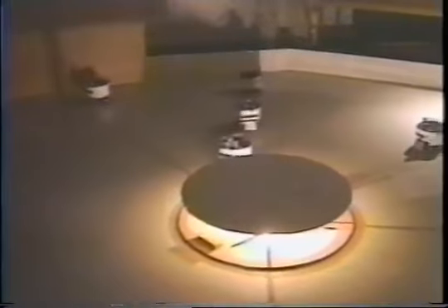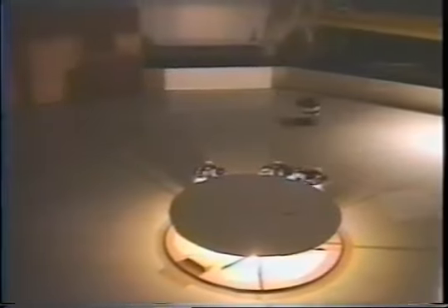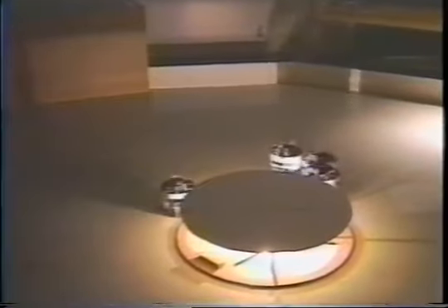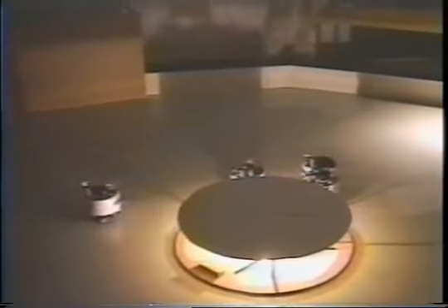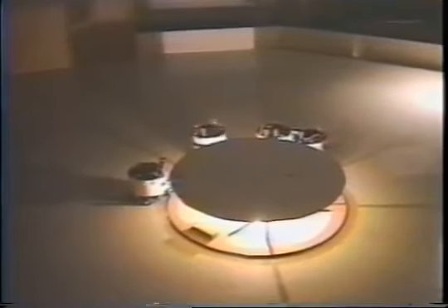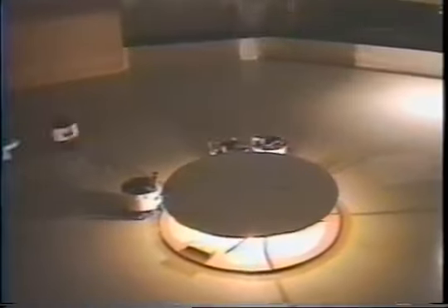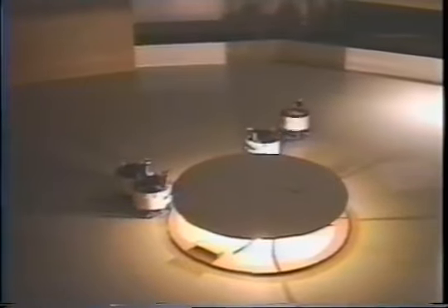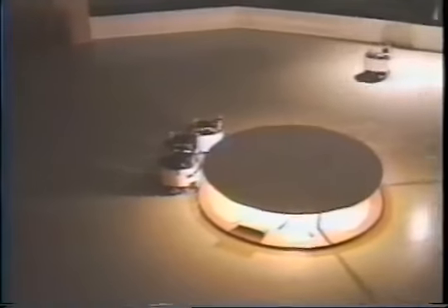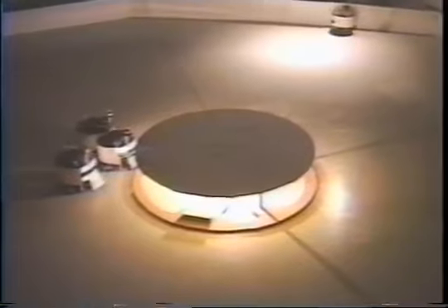The robots do not explicitly communicate and are not centrally controlled. The robots also do not differentiate between objects and other robots. 6 robots starting from a random initial position must locate the box using 2 forward-pointing light sensors. Once a box side is located, the robot determines if the box is between the robot and the goal using an upward-pointing goal sensor and either pushes or repositions itself on the box.